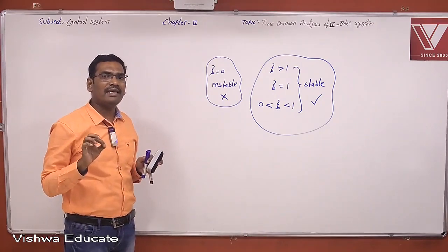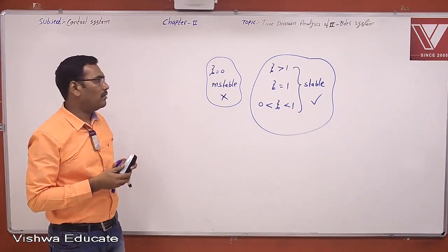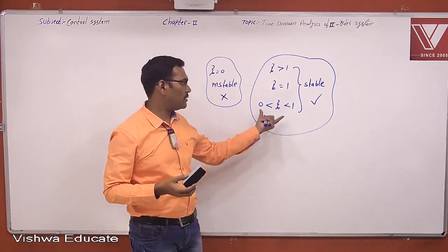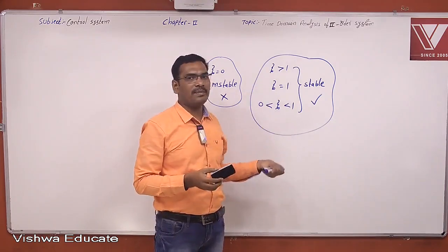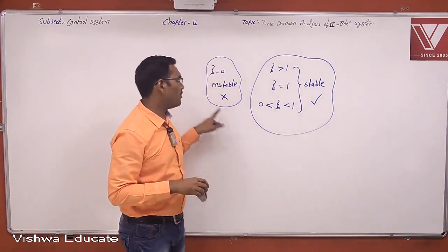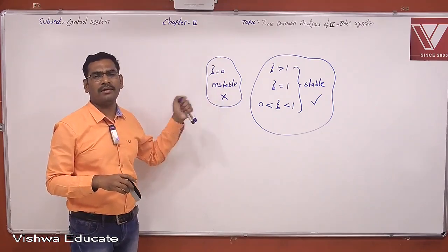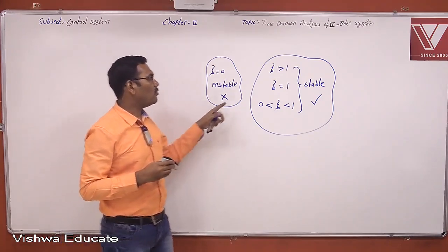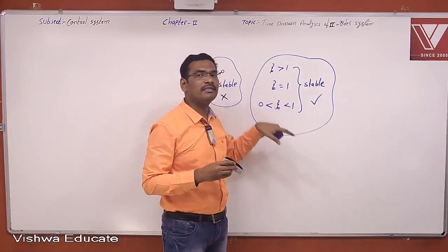While you are designing a second order system, keep 2 points in your mind. One is what should be the best damping factor zeta. All are best at present because all are stable. But one is out of the list because it is marginally stable and very, very close to instability. We never use that. So among these three groups, which one is the best?